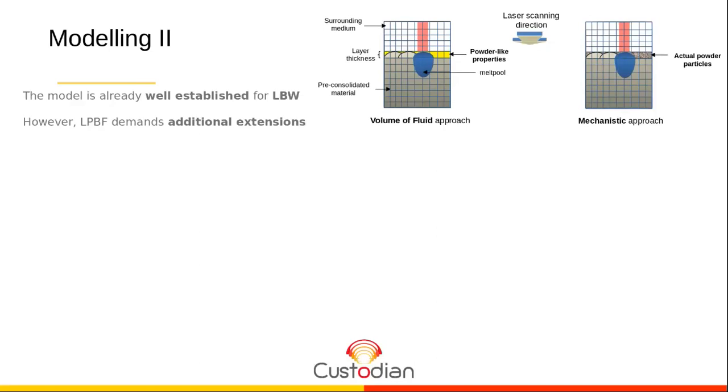That's something challenging, because we mostly work with mesh-based models like volume of fluid and finite volume, and you need a very, very fine resolution in order to be able to simulate domains that are representative enough for attaining the heat accumulation effects. And that's why we have a second approach that uses the concept of porosity in the layer. We try to put the volume of fluid layer at the top, whose physical properties are adjusted to resemble the absorption, the heat conduction, and so on of the actual powder.